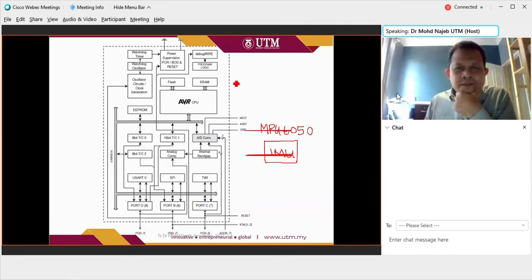So in this single chip microprocessor, you have your basic microprocessor with the RAM and ROM, and then you have your AD converter, and serial communication interfaces, UART for you to interface with other boards physically somewhere else. Then you have two extra interfaces to communicate serially between external ICs. You might want to add external ICs, but you cannot use SPI and TWI for long distance data transfer or communication.